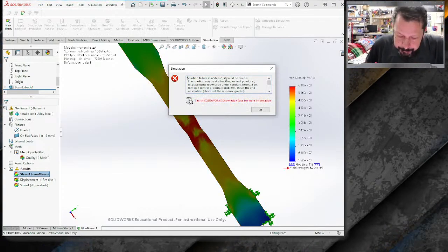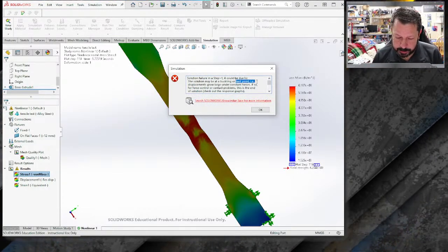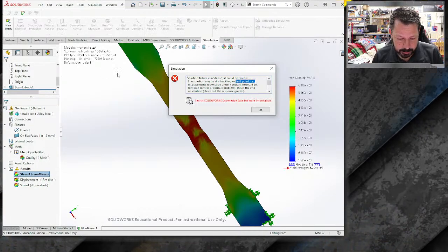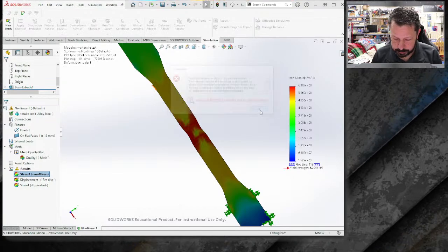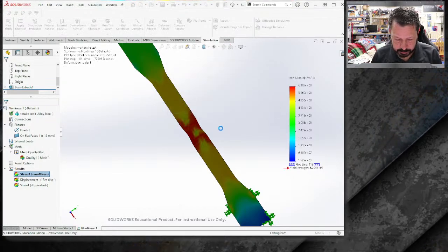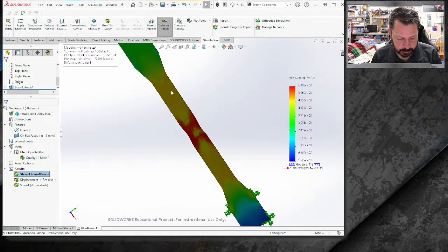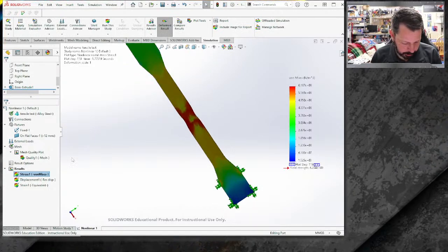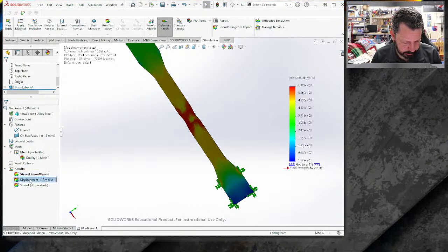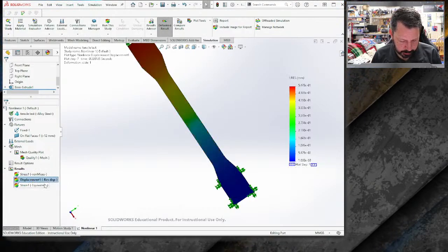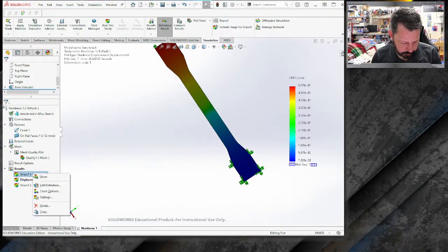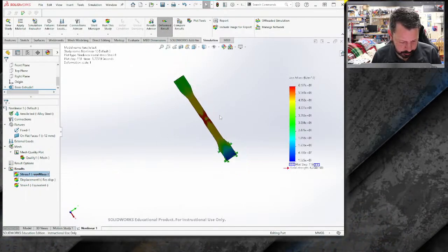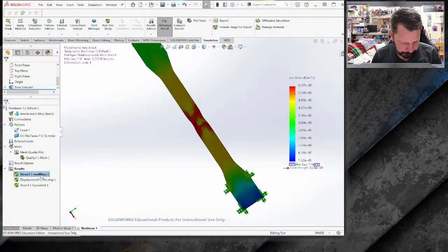So there we go. It made it to a limit point here. So it is 1.77 seconds. Let's see what it did. It took 119 steps, and we could go in here, show our displacement. Well, which one do I want? Let's do this von Mises stress one.